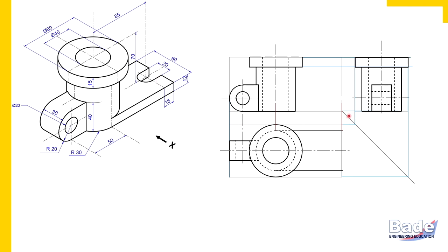This is the base plate of height 12 millimeters, so 12 millimeters to be measured to draw that strip. So this is that rectangular strip, 12 millimeters. So this rectangular strip like surface now is ready. But yes, you have guessed it properly. Two visible edges don't intersect, so correction is required.